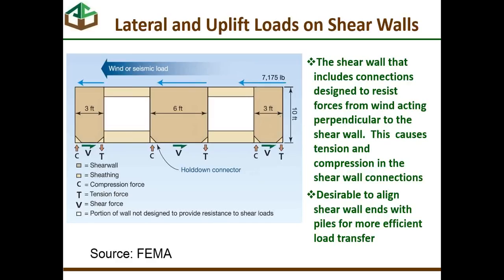So this is the perforated method. It means lots of hold-downs. In this particular wall, again, it means 6 hold-downs. And the difficulty here in real construction is that you have to pretty much align these hold-downs for tension and compression either at piles, or you're transferring a load, a compression or a tension load, into a beam that's not at a pile. So it's an important consideration there.